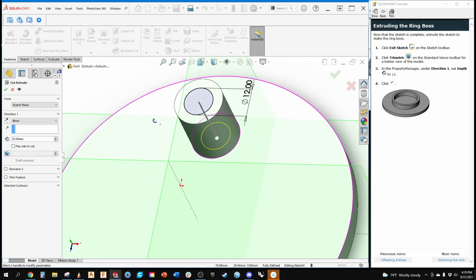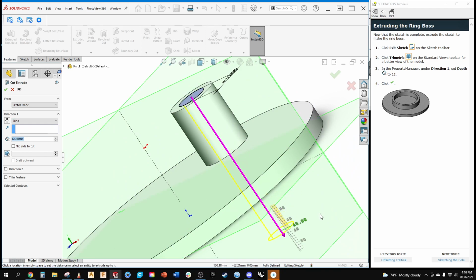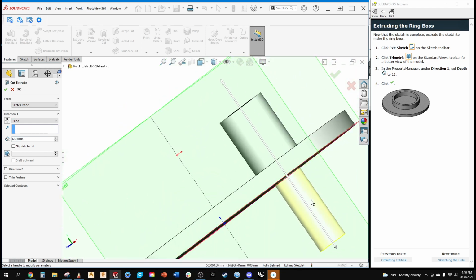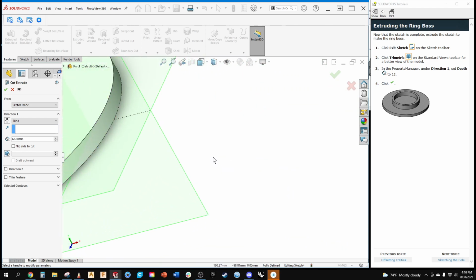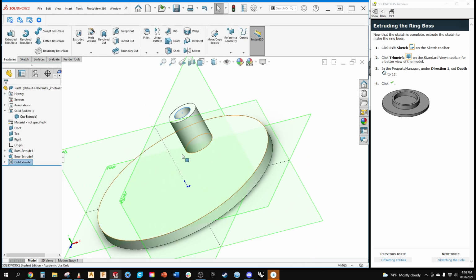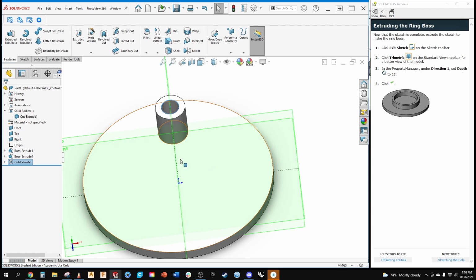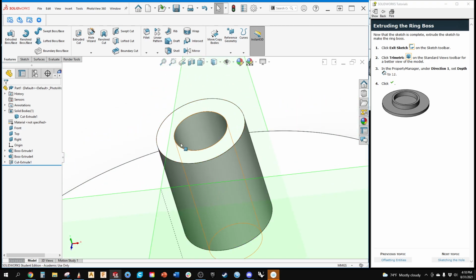Exact same thing. Now what it's saying is, what is the sketch plane? We already had that selected. How deep of a cut do you want to do? So we're just going to do blind at this time, and I can drag it. I want to make sure it goes all the way through. So I'm just going to go really, really far. Let's hit select. So there it is there. Well, I also want to put some radiuses on this. So let's put a fillet in.